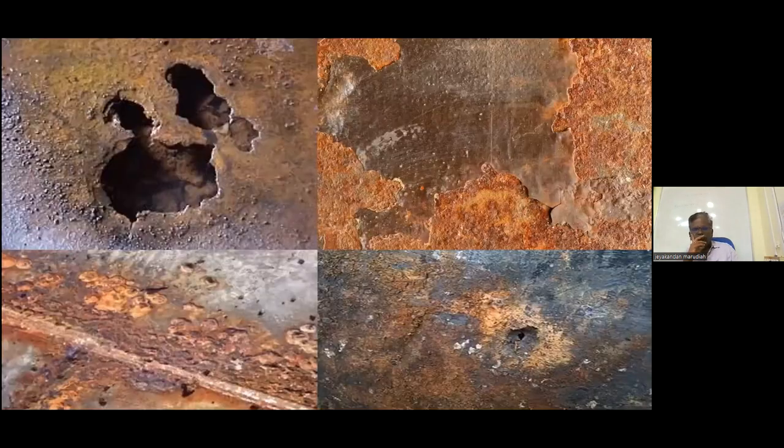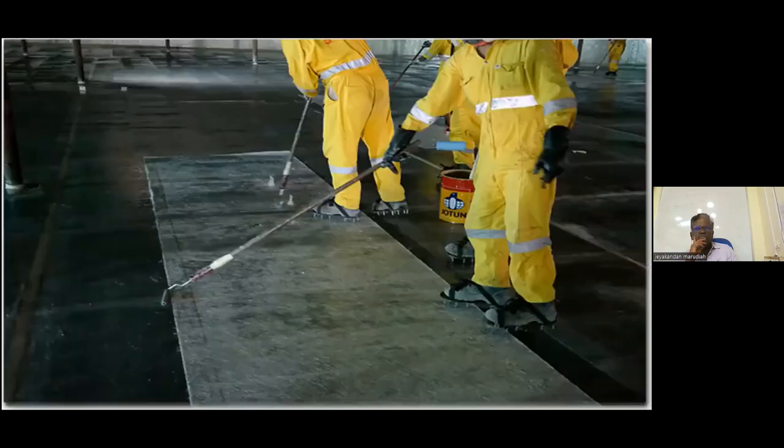If an above-ground tank bottom is corroding, it must either be replaced or coated with a thick film, fiberglass reinforced lining with a 60 to 65 mil dry film thickness. Since replacing a tank bottom can be costly and time-consuming, fiberglass linings have become a popular alternative for tank bottom repair. GRE lining is a significant application in the fiberglass industry.